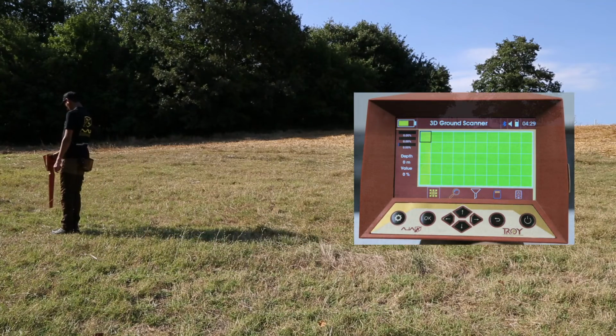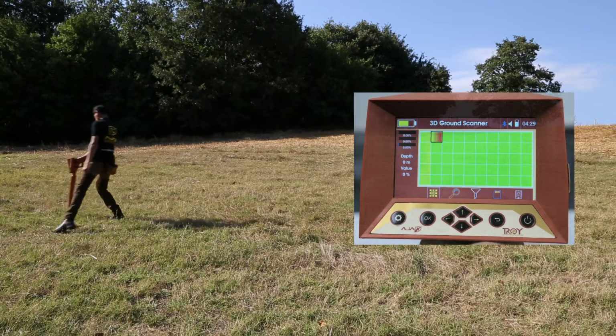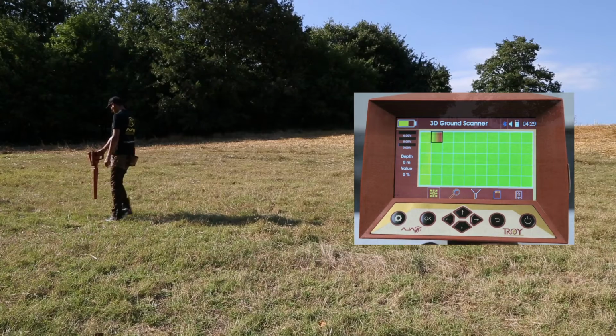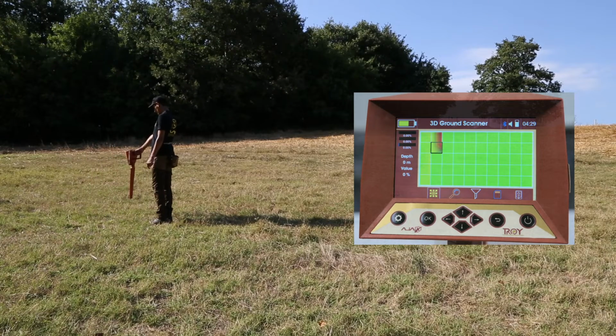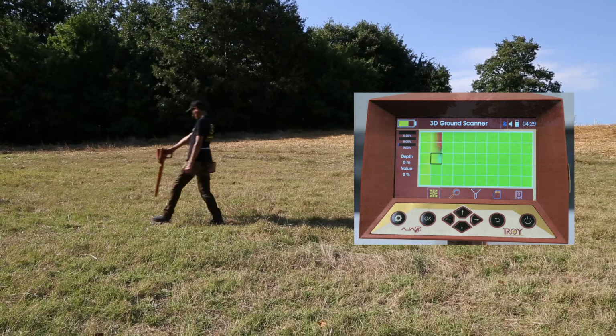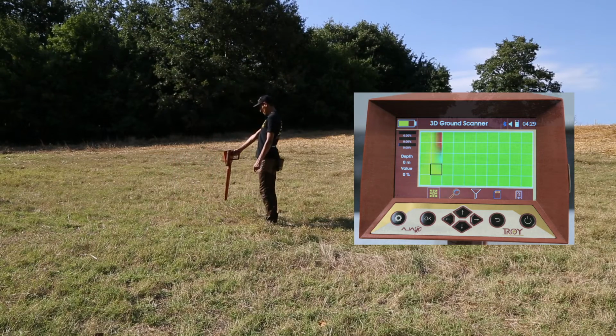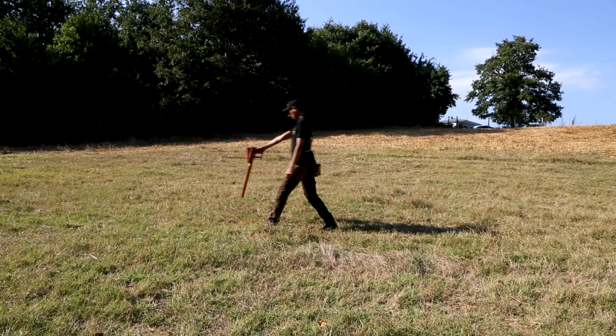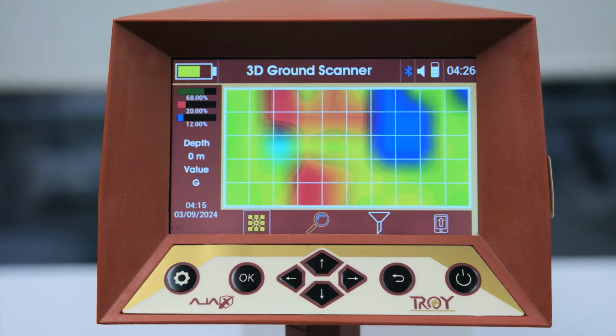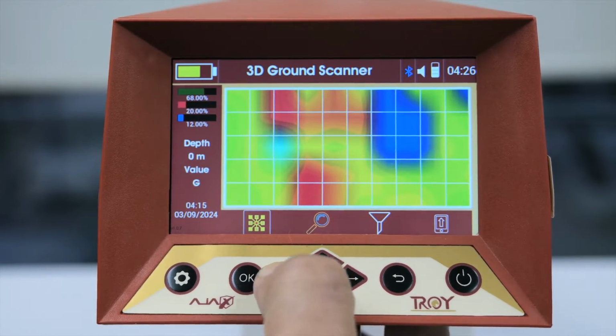At the end of the column, step right to change the column. When you return, press the handle key again and continue scanning. Then go back in fixed steps and stop in each cell until the column is over. Repeat these steps until all cells are filled on the screen. The device will begin processing the data when the entire scanning area is covered.